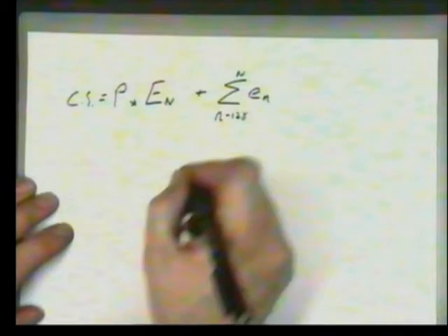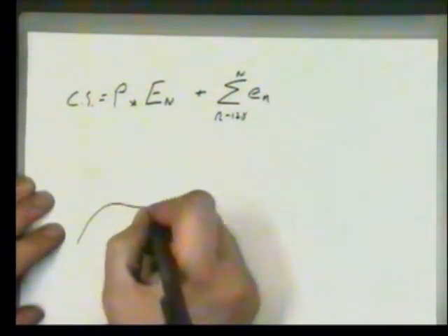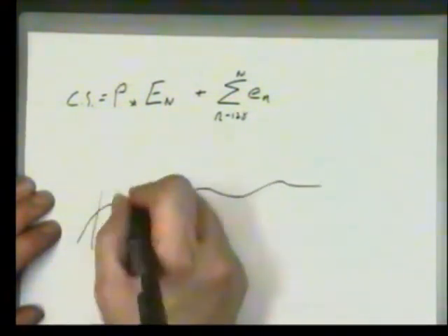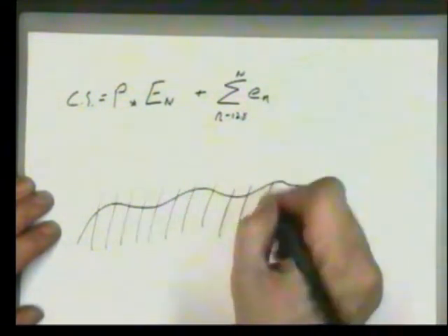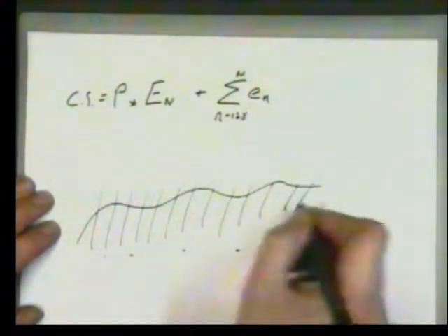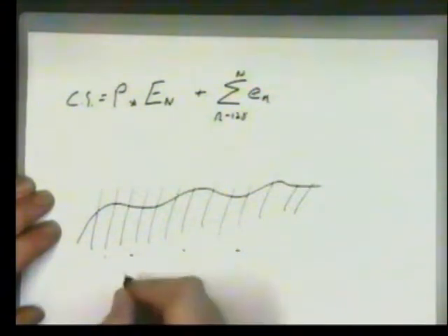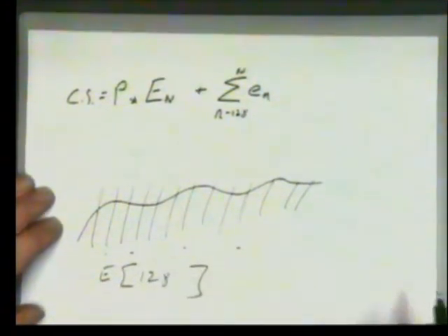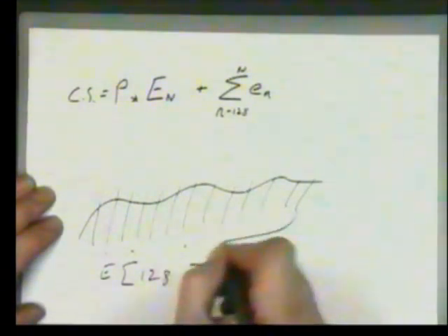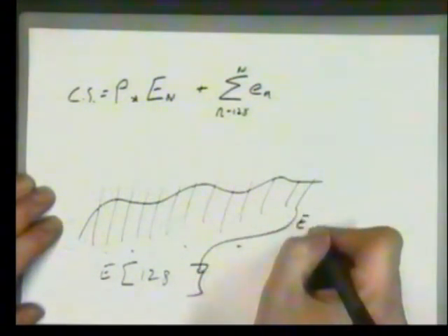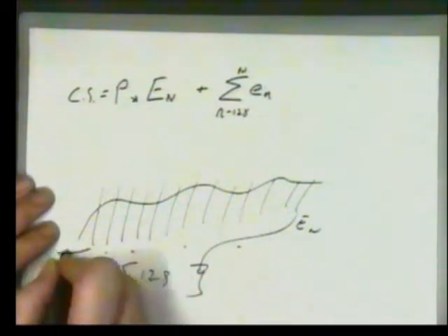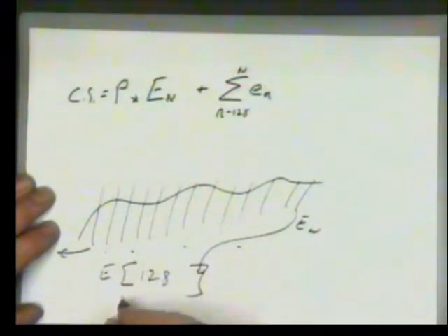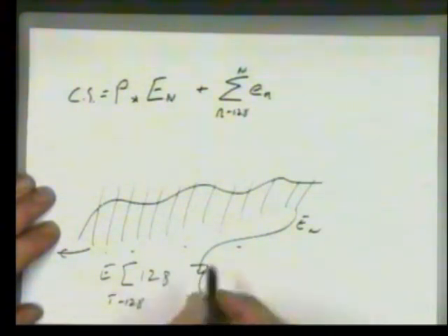Because what we do is we've got a continuous error signal. What we have to do in our computer is take samples of it at regular intervals. And if we store these samples into an error array of, say, 128 elements, we drop in the most recent sample at en, losing our oldest sample. So we have in our array all the samples from time now to time minus 128 samples ago.